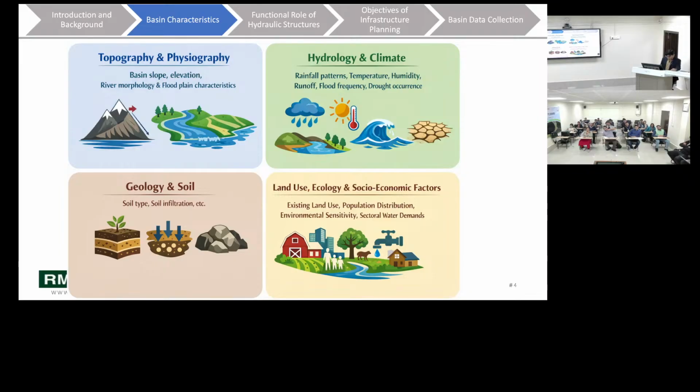Like if the public works department is planning to construct a highway, then they do pre-feasibility, then feasibility, then approval, and they may face several conflict issues, social settlements, and compensations. So these are the issues. If you are planning to design a larger scale project, then you should consider all these aspects. Otherwise, at department level, if your purpose is a small scale structure design, then you need not consider all those aspects. The topography, elevation, morphology, what the river morphology condition is, then floodplain characteristics, historical flooding scenarios.